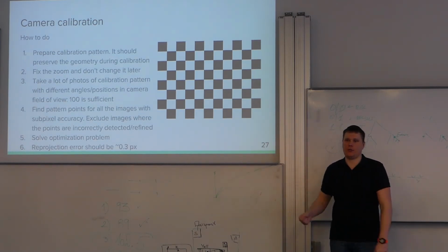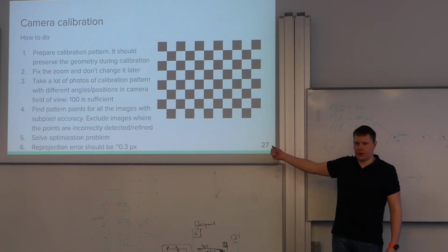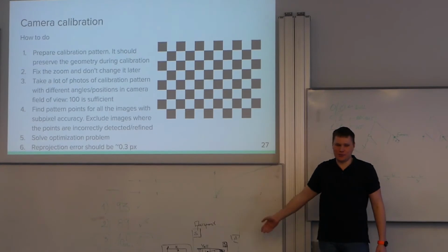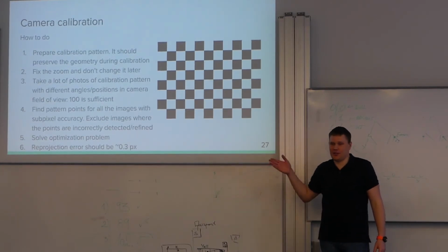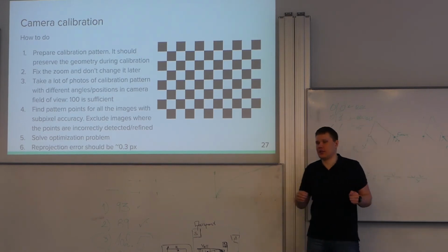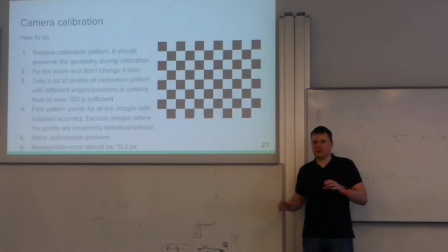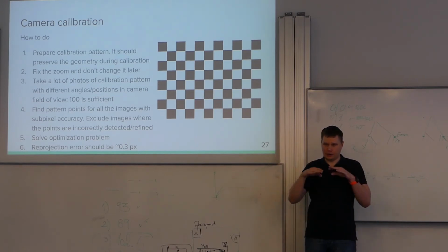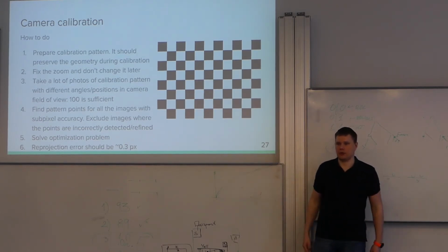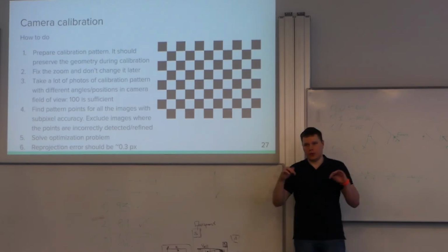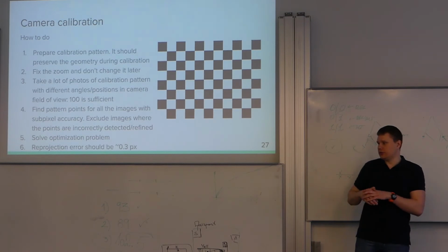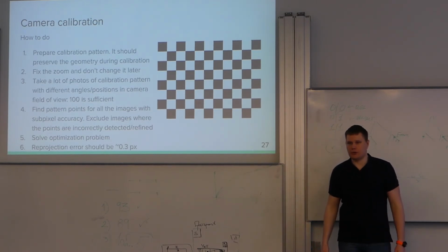So we can do calibration actually with one frame, but it would give very poor calibration parameters because we didn't cover all the corners. We aren't able to recover the actual distortion function for the corners, but it may be important because the object is not in the center of the image all the time.